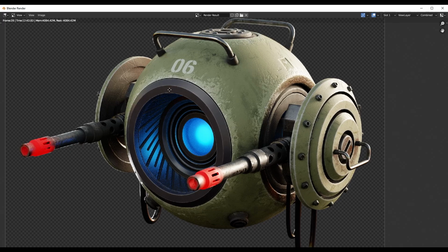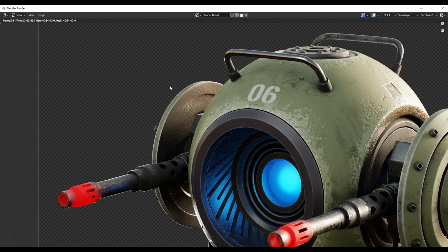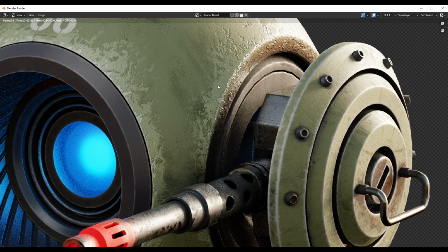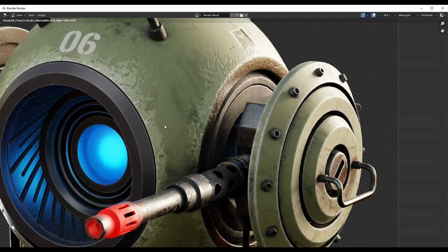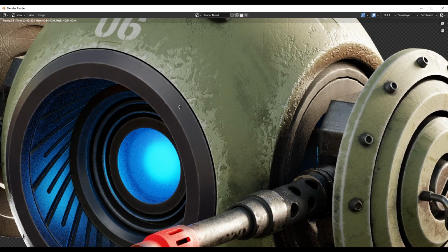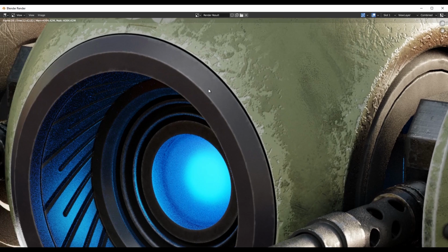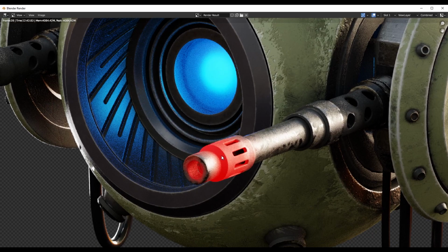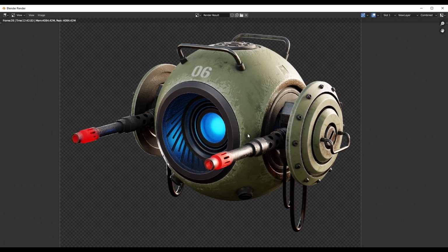The thing I'm going to change is I'm going to delete these scratches inside the side part, and also I'm going to add this height difference inside the side part too, and I'm going to add some more edge wear into our frames. And maybe I'm going to decrease the roughness from this hot reddish part. So I'm going to change this inside Substance Painter and go back to Blender and test the render again.